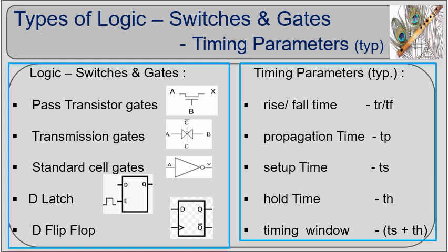Transistor parasitics like resistance and capacitance, along with the load capacitance, create RC delays. Also, the voltage degradation due to MOSFET threshold voltage further aids in creating delays like rise, fall, and propagation delays. Some of the popular logic gates, along with prominent timing parameters, are shown in the figure.